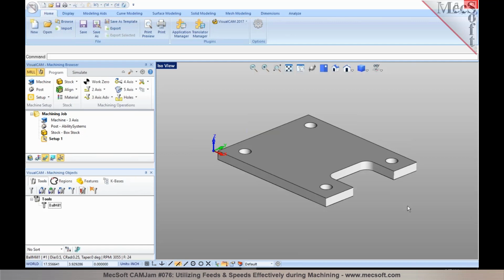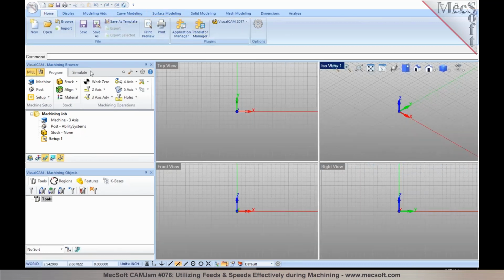But if your machines can handle inverse time feed rates, like G93 to toggle on an inverse time feed rate, and G94 to toggle it off, we could be using inverse time feed rates to program feed rates for 4-axis, and for that I'm going to give you a quick example of how that is done. So as Krish gave you the math behind the computation of inverse time feed rate, I'm going to show you with an example of how the inverse time feed rate is computed and how it's done in